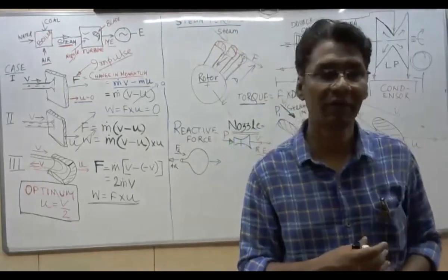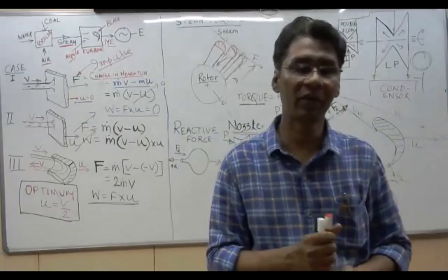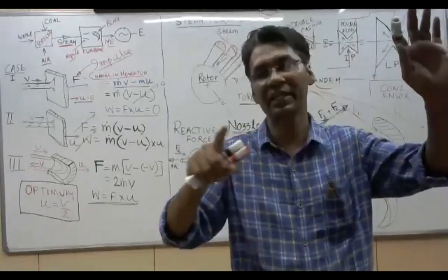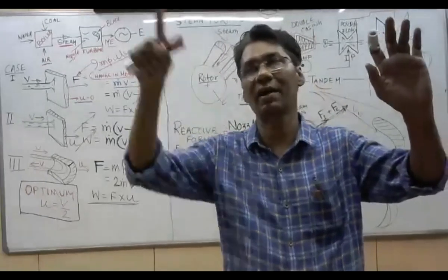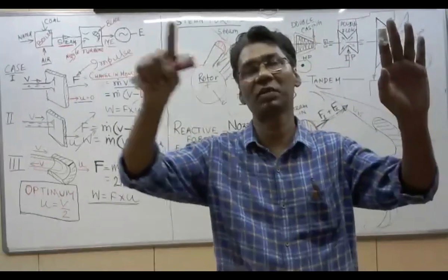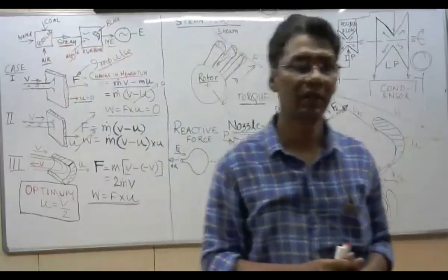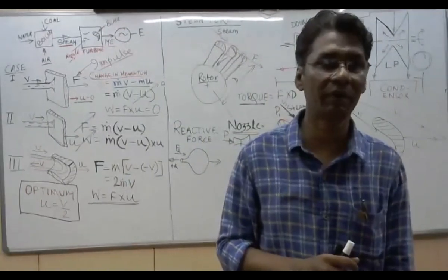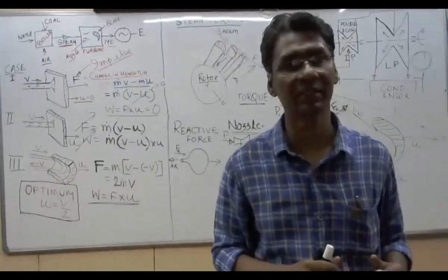The size of blades differs across the turbine, because the high pressure steam's pressure is continuously getting down. That means the blade size is getting bigger. If the pressure is getting down, the volume is getting higher, so the blade size goes higher. The jacking oil pump and lube oil pump will be discussed in different classes. Next.